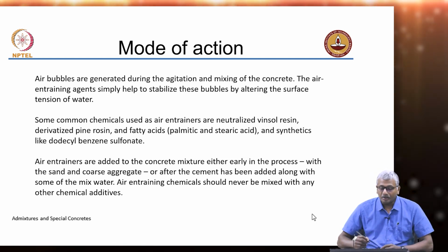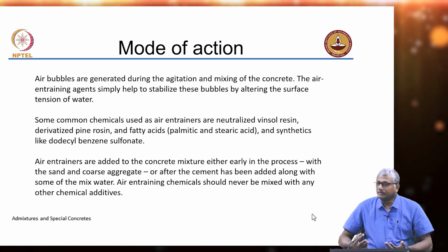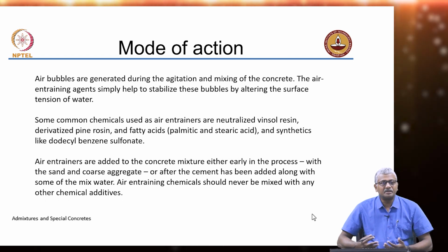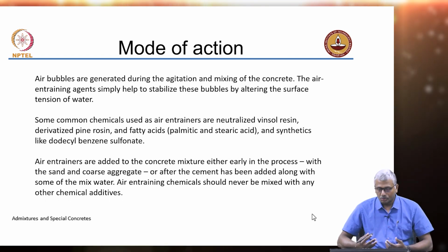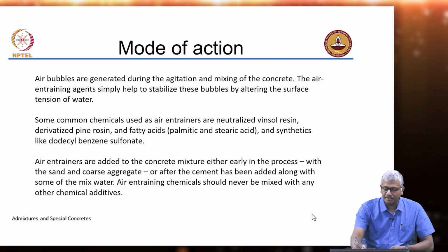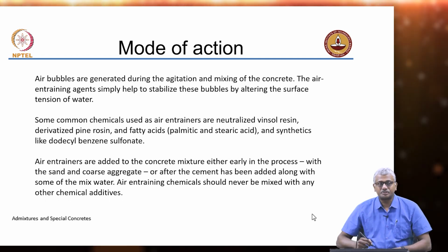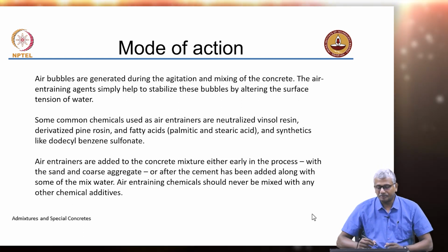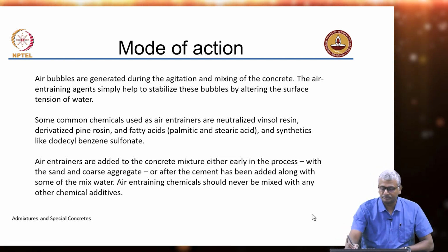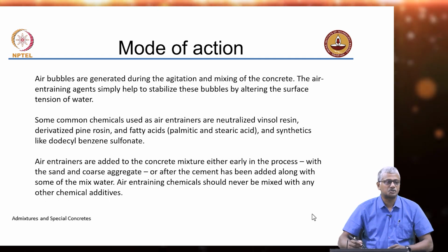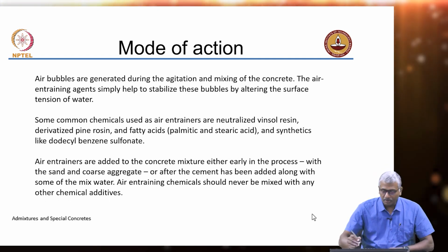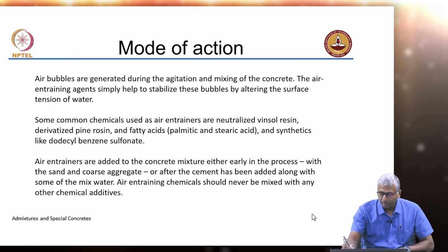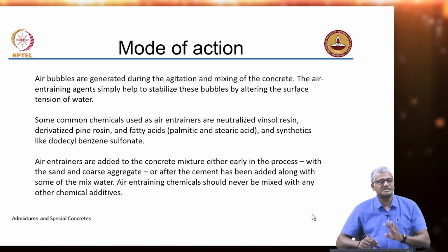Now, in the kiln, as we discussed earlier, there is going to be a combination of these oxides to form the primary phases: tricalcium silicate, dicalcium silicate, tricalcium aluminate and tetracalcium aluminoferrite. If you look at the overall composition, if you add up your C3S and C2S together, typically around 80% would be C3S plus C2S, irrespective of the type of cement.